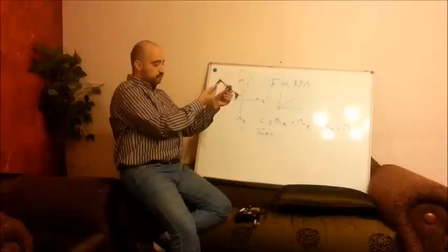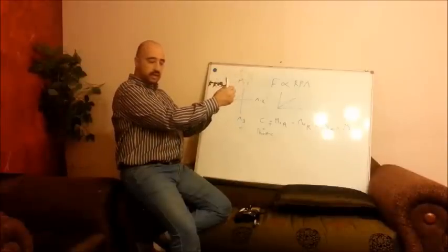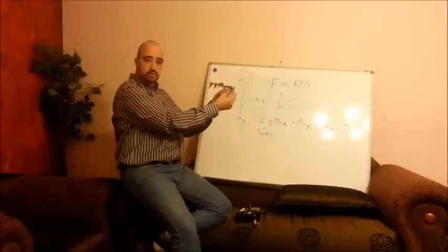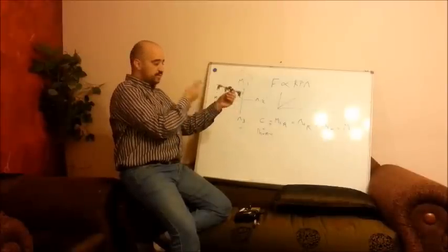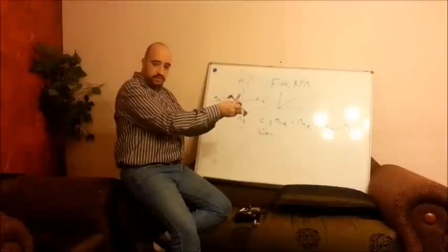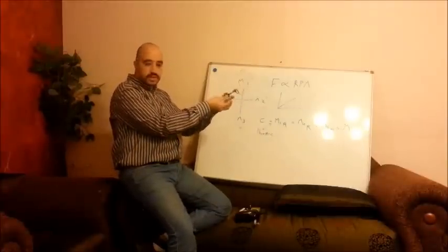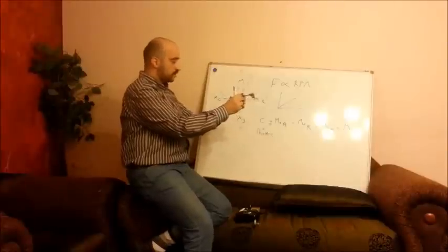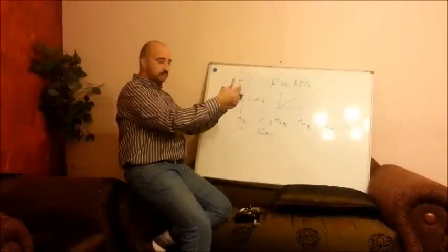So when I push it like that, this motor will increase the RPM to give more thrust and to be able to balance it. Because without that, if I push it like that, it will just flip and rotate, because nothing will stop it from rotating.